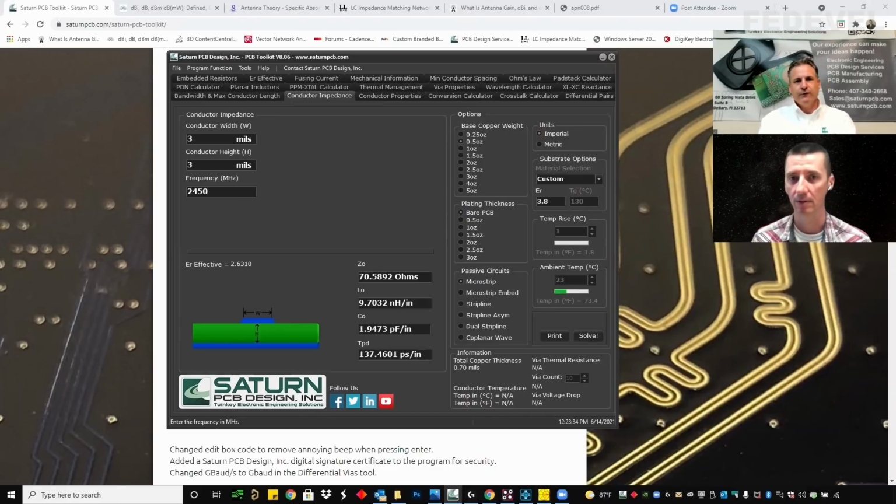That's exactly what the problem is. Even the EM simulators built into Cadence and Altium, yeah, I'm not going to say it doesn't matter, but you can spend a week simulating something just to make sure it's at 50.000 ohms, and you're going to manufacture, and you're going to be like, what's going on here? It's off.